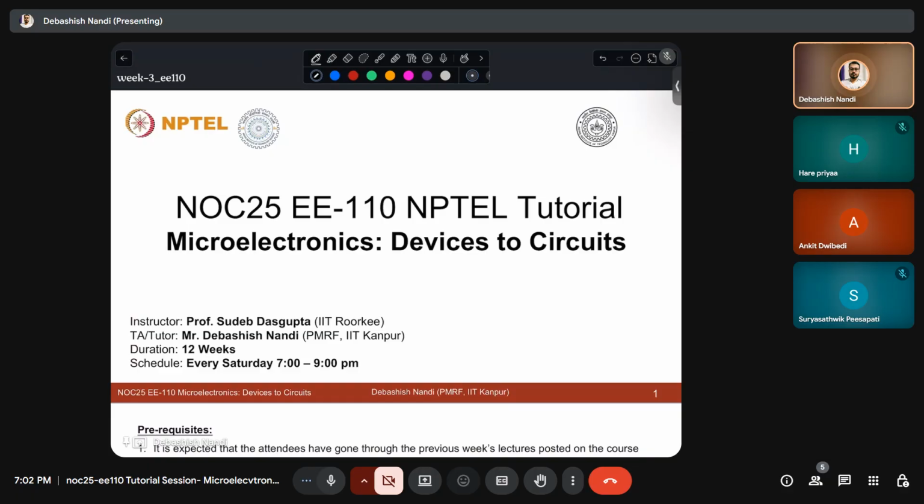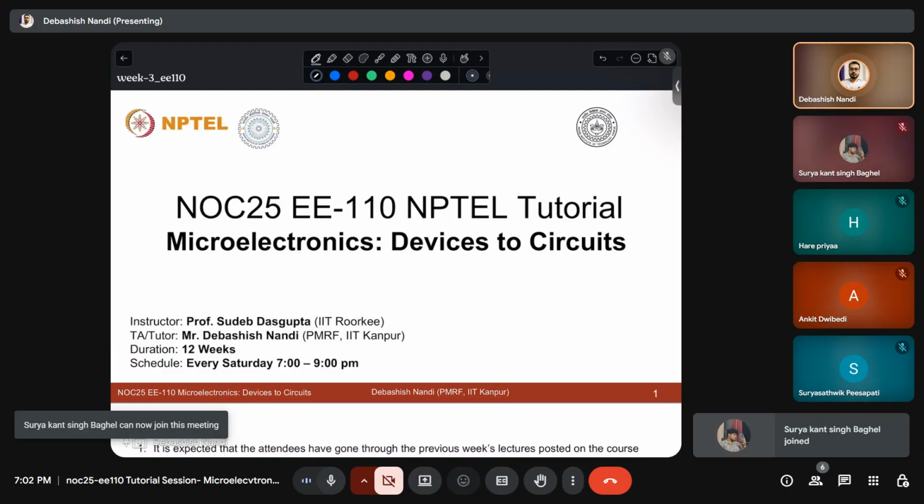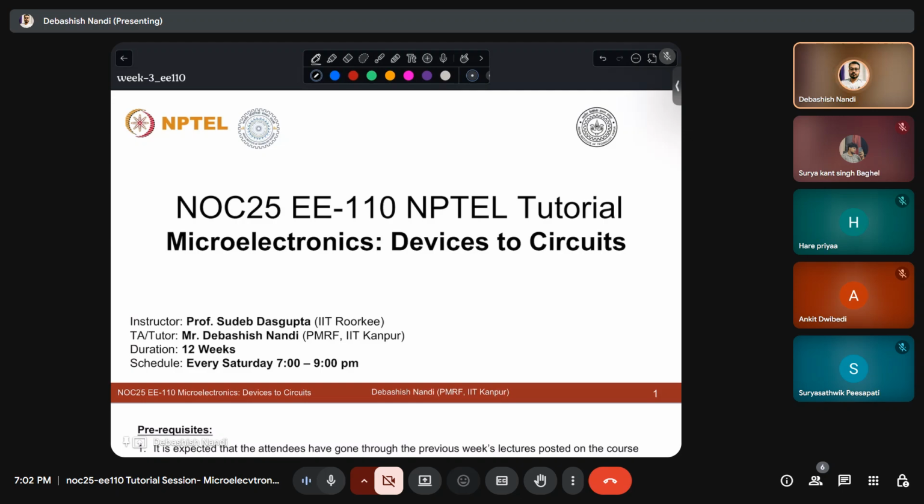Yes. If you go to the lecture 2 material on YouTube, there is one comment from me, and I think it is the only comment on that video. There I have posted one open source PDF, where you can get the step-by-step process of how that vertical BJT is fabricated. The bottom one, the P plus or highly doped region, is done with a diffusion process, or normal dopant diffusion, into a pristine silicon wafer. And the lower doped portion on top of that is done by a method called epitaxy.